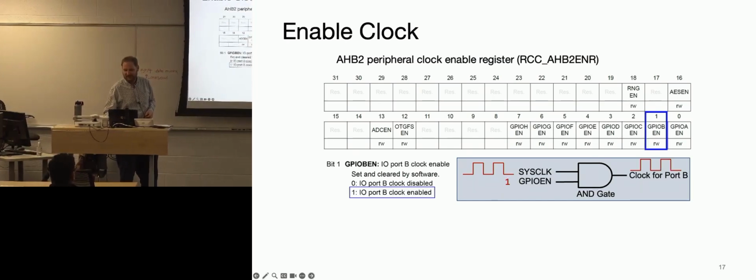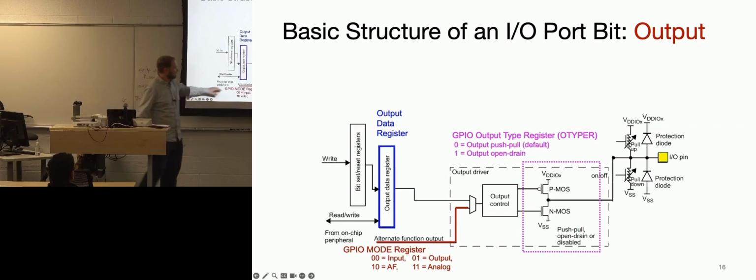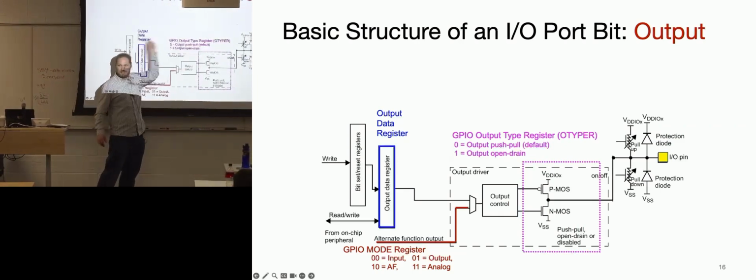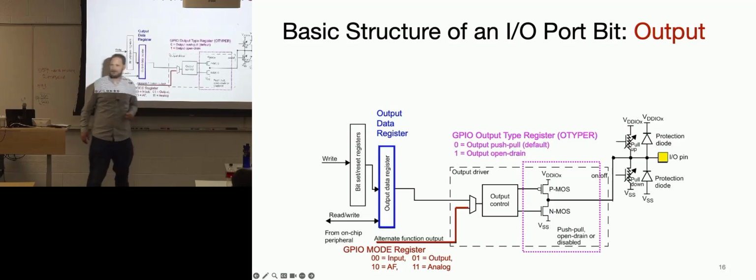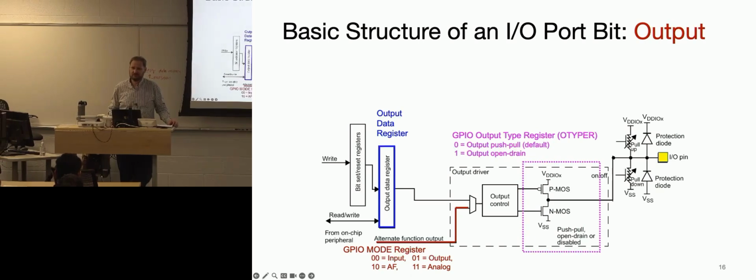To read it in analog, I would assume you would need to pass it through an analog to digital converter. Yep. So you would want to read more than 1 bit. This is just controlling that. I think there's a slide on the analog path, but it would go to an ADC or something. If you were reading digital, you would only be reading 1 bit.